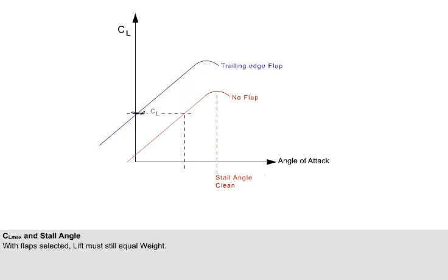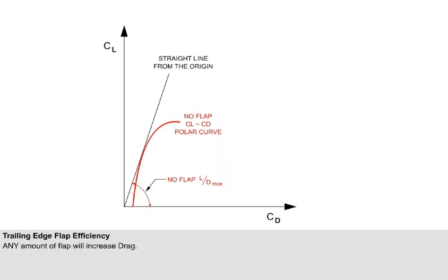As the flaps deploy, the pilot must reduce the angle of attack so that the effective angle of attack remains constant and that lift still equals weight. Please remember that any amount of flap will increase drag.